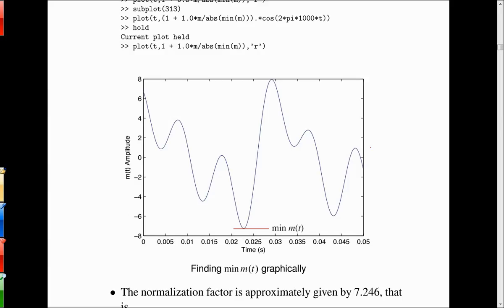So it's constantly varying? It's constantly varying the gain to try to keep it at the constant, at the maximum amplitude level, because they're trying to get as much modulation onto the carrier as possible to ensure that you can hear it. Because if it gets too weak, then you know you're tuned onto a station, but the modulation is so weak that you don't hear it.